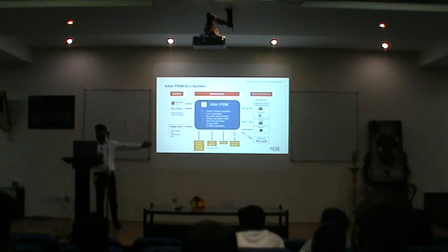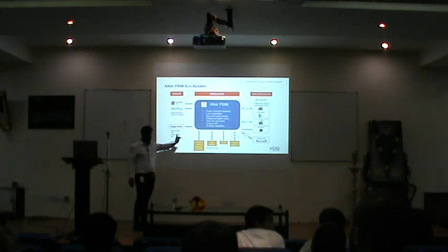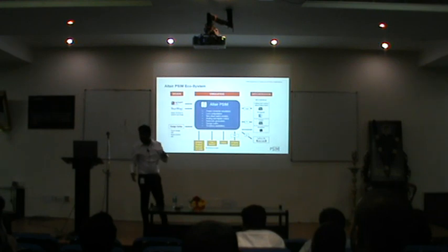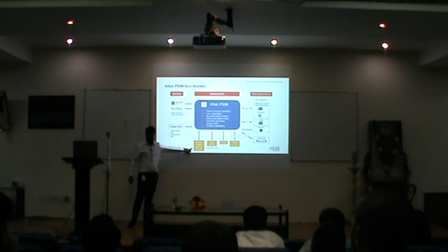There's also code generation for doing control implementation on hardware targets, like multiple control targets you can implement. We have different targets like Typhoon HIL. In case you want to deploy control algorithms on Verilog or VHDL, there is another provision. One is the embedded side, another one is Verilog and VHDL, which you can interface with ModelSim. And then you can do co-simulation with MATLAB Simulink.